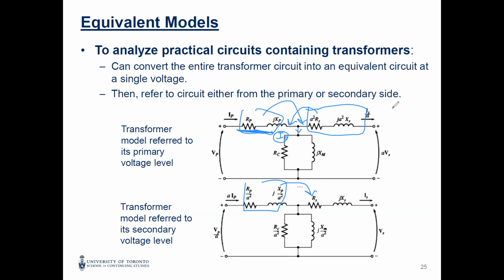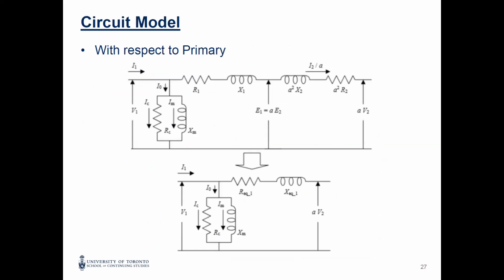It's a kind of approximation. It will not be exact, but it's a good approximation. So you can see here what I did. I moved the one for the primary, R1 and X1, to the other side, to R1 and X1 here. Then I have real and real, and imaginary and imaginary. So you add the real plus the real and imaginary plus the imaginary. You get something called the approximate equivalent circuit.